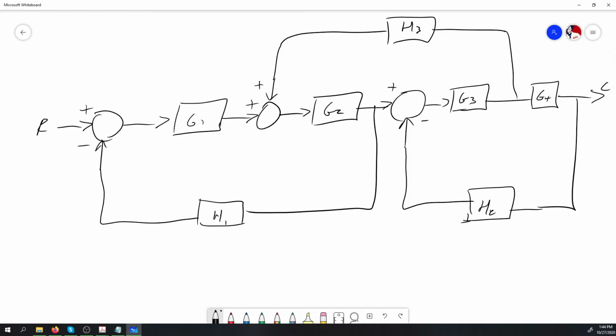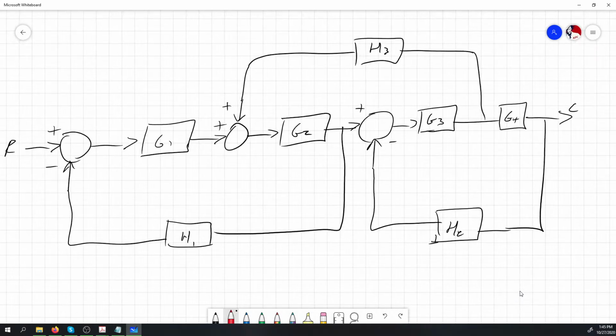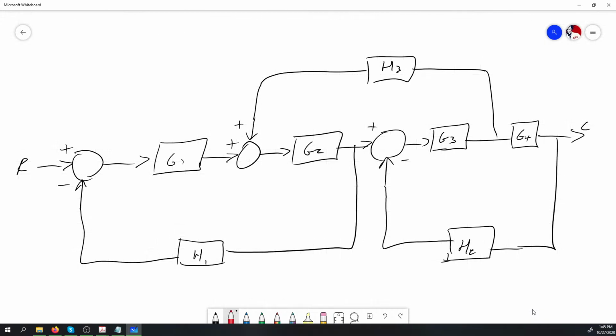Yeah. Alright, nice. So that actually should be our block diagram. Yeah, that's our block diagram in particular. So our first step would be to move this particular takeoff point here to the right of G4. So drag this right. So I'll move this takeoff point to the right of G4. So I'll be going this way here, drop in that takeoff point here.